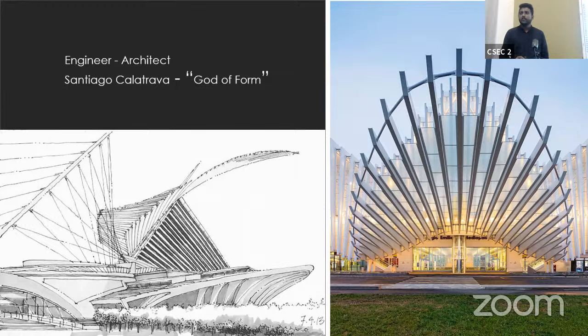Okay, you have a 150 wall in the architectural design. You put a 225 column in that 150 wall. Here comes the column out of that wall. That's the spatial quality of that space gone.